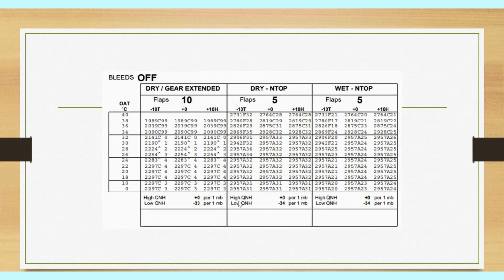So what's the rule again from the excerpt I showed you, and what I did before I even showed you the excerpt, is that you find the closest but the highest to our actual takeoff weight, which is 27,640 kilograms. Excellent. And then the last thing you'll do here, as you might have correctly guessed, we have to work out the temperature that corresponds to this weight, and that temperature is 40 degrees.